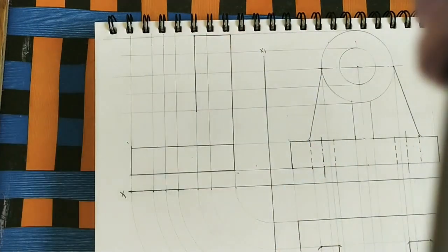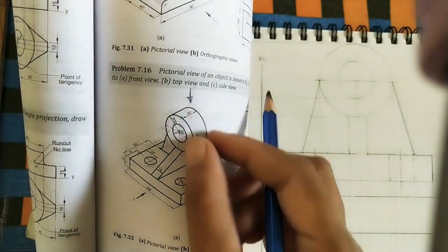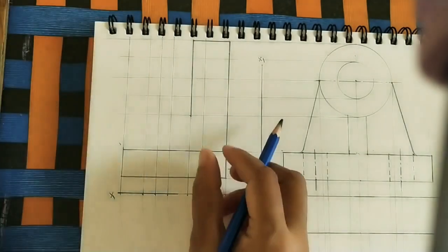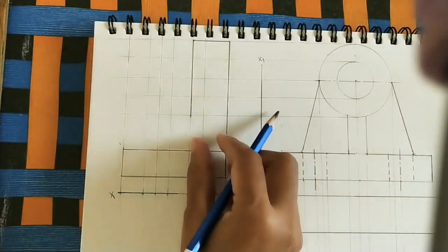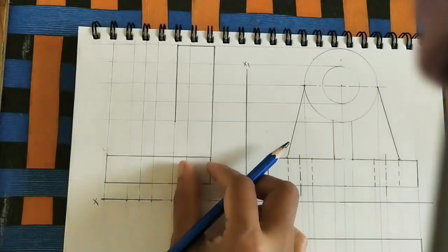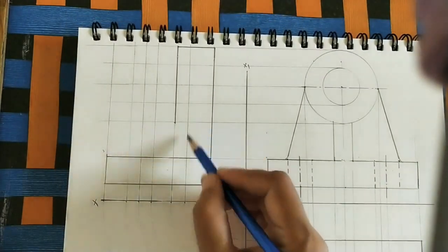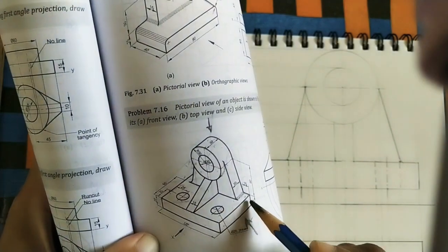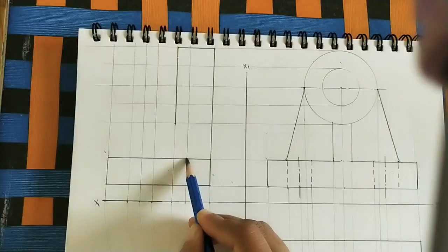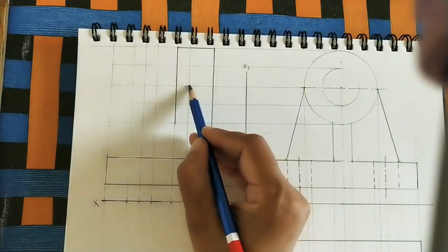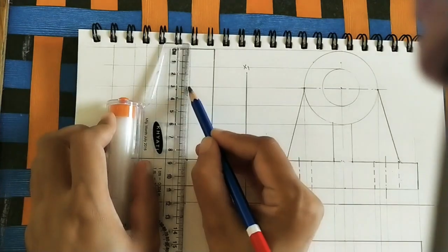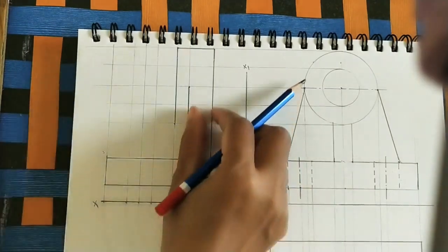After that, on the side we can see this thickness also. How much height is it? 60 mm. How much thickness is it? 20 mm. Now here we can see one more line. 20 mm we have to take from this. 20 mm thickness, so same thickness we are taking. Above this thickness, we have to take 60 mm up to the center of the circle. So from this point to the center of the circle, up to here we can see this line. Just make it dark here. So we can see this thickness from the side view.